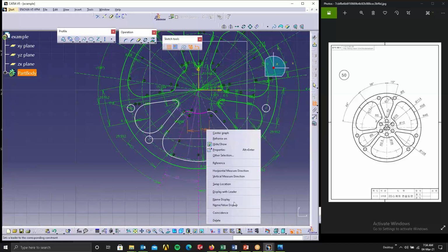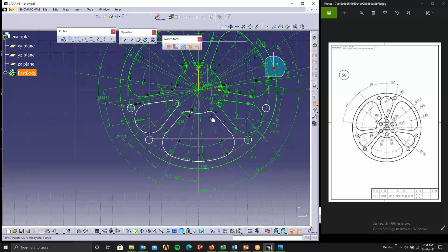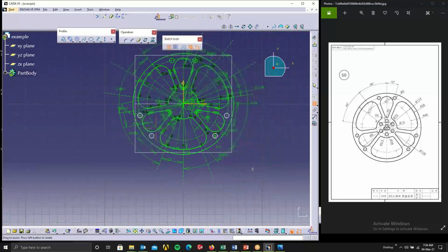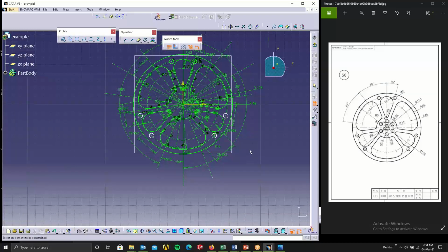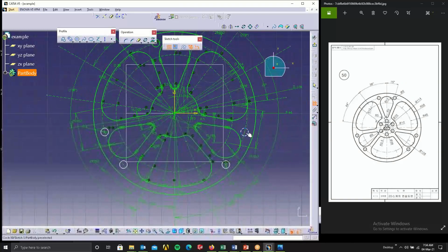So a constraint. Delete this. This we can do. So you can see resolve constraint. Now all that remains is this part. So just see why it's not constrained. This constrains these two dimensions. This one dimension and this one dimension you can do.